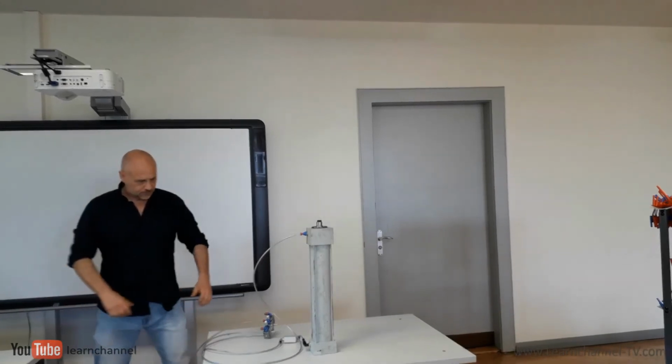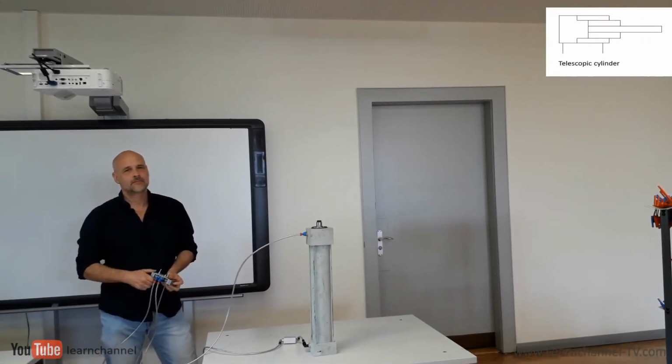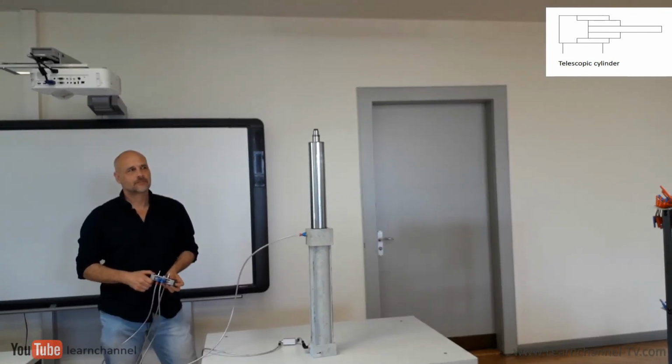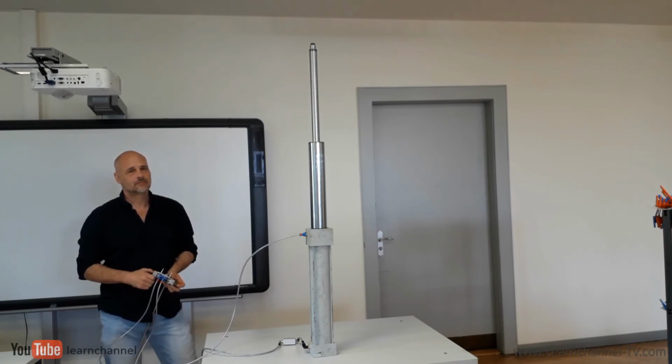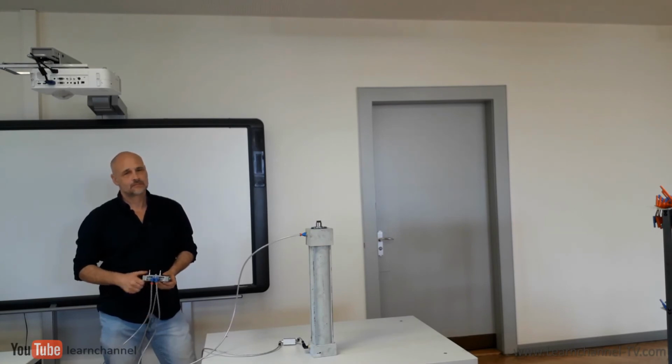You need extra distance? Then take a telescoping cylinder. Also called a multi-stage cylinder, this type of cylinder consists of a series of tubular rods called sleeves. These sleeves sequentially decrease in diameter and are nested inside of each other. Once pressure is switched to the cylinder, the main sleeve first extends. Once this sleeve is fully extended, the next smaller one begins to extend.